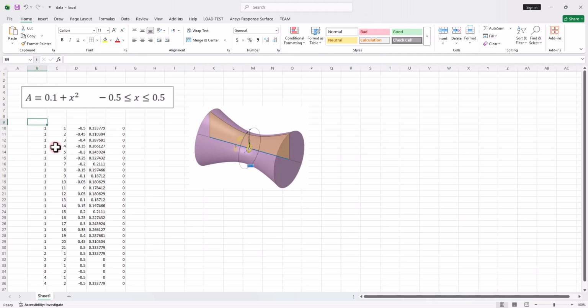So this is the template of the Design Modeler software. In column 1, we've got the group, then we've got the points, and then comes the x value, next column the y value, and finally the z value. Of course, due to the symmetrical shape of the nozzle, we are going to just model half of it and in 2D space. So there wouldn't be any z value. And then we know that you can use more points in order to create the curve. The more points that you use, the more accurate the geometry will be.